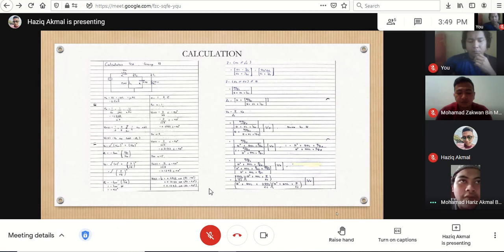And then our Vs, which is 1 over 2 plus 2 over pi sum of 1 over n sine n pi t. And then we will insert n numbers, which are 1, 3 and 5. For n equal to 1, Vs will be 2 over n pi with angle negative 90 degree, and the result we obtain is 0.6366 angle negative 90 degree.